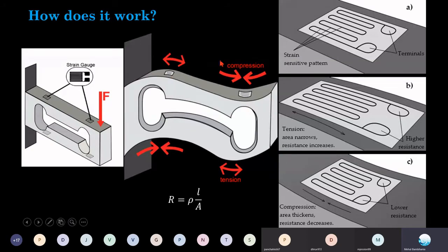See how this looks. You see on the very right-hand side, this is figure A indicating the natural or neutral position. Without applying any load, the strain gauge looks like this. This is the circuit of that strain gauge. Through this circuit, we can get the initial resistance value. So this circuit has a certain initial resistance value, and due to that resistance, this terminal indicates a certain voltage. If there is no resistance change, this terminal indicates 0 voltage.